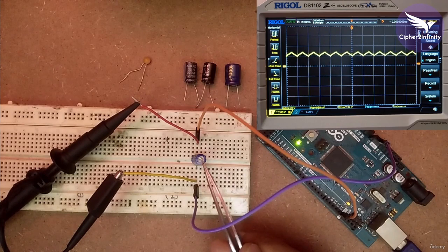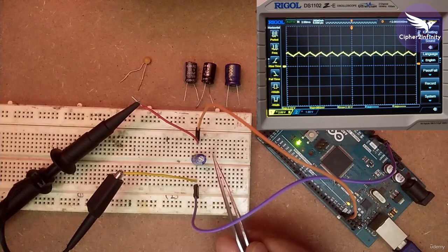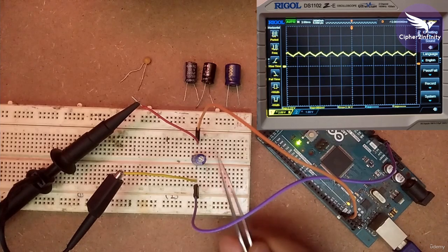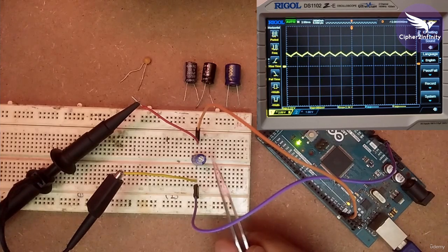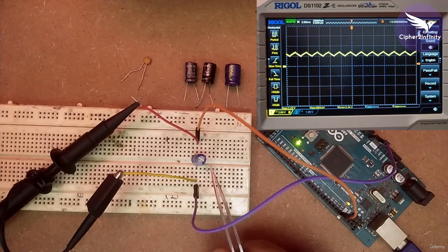Now this capacitor is providing a lower impedance path to this 500 hertz signal, but still the impedance provided by this particular capacitor is not in milliohms. It's around ohms, let's say 50 ohms or somewhere around that. To get the exact impedance this capacitor is providing, you need to refer to its impedance versus frequency plot at 500 hertz.